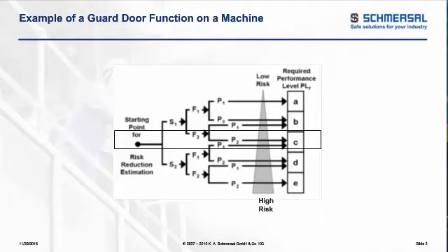But ultimately, for this webinar, it's just getting down to a point of knowing what we need on the machine, but what do we have to look at downstream when it comes down to the solution, thus understanding machine safety functionality. So we're going to take an example of a safety-related stop function initiated by a safeguard. And for our example purposes, let's say our selection criteria, we know that the type of injury that can occur, maybe it's a crushing or an amputation of a finger, so we select S2 in this particular example.